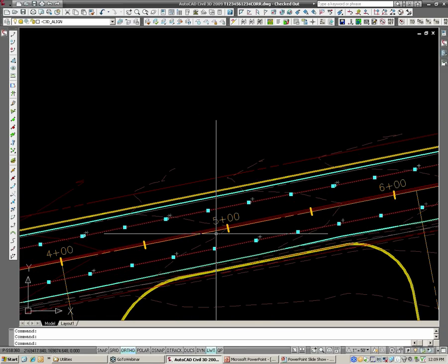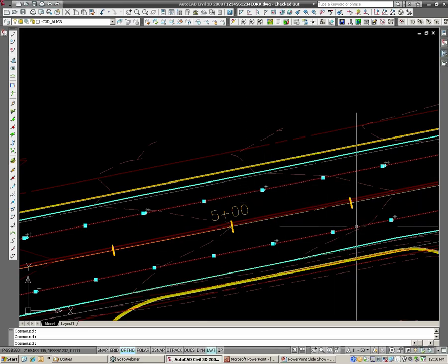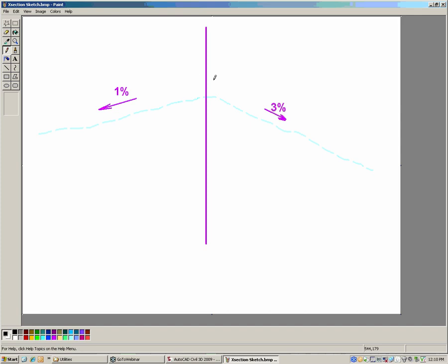So essentially we have a profile down the center of the road with elevation, and a profile down the left edge, and a profile down the right edge. Well, because in central Pennsylvania, at least for the district that this was submitted to, the way you do an overlay and widening is pretty specific. And what you get is a scenario that you need to adjust based on different design criteria.